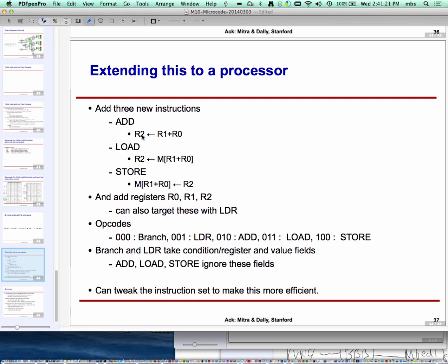So typically in a computer, you are going to have what are called register banks. A register bank is nothing but a little memory, except that it's a writable memory. In this case, let's say I have a register bank with 4 registers, 0, 1, 2, 3. Each one of them is, let's say, a 32-bit number. And then I may define an instruction where the first 3 bits tell what operation it is.